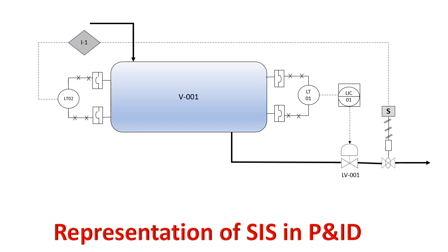So basically, you want to maintain the level here, and for maintaining the level, what has been done? We are measuring the level first. The level measurement instrument is generating the PV. There is an operator giving you the set point, and the set point goes to this level valve, and it gets opened or closed depending on the level. In most cases, this is how the level is maintained.